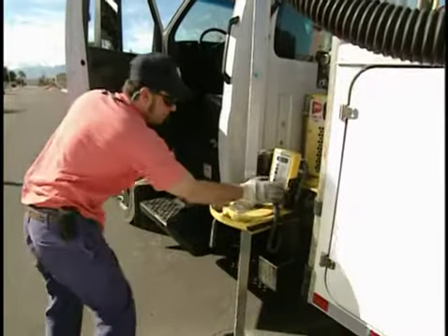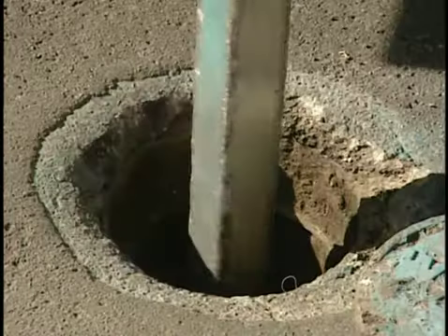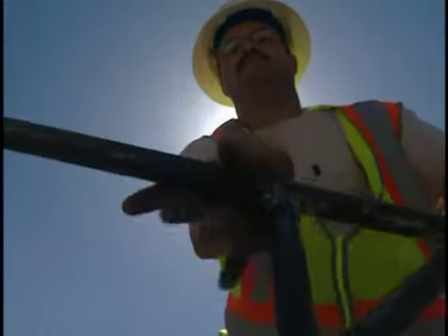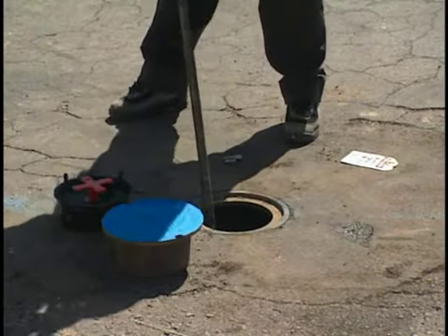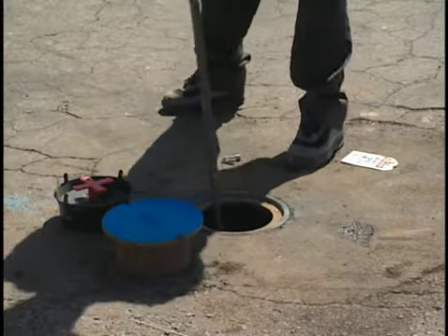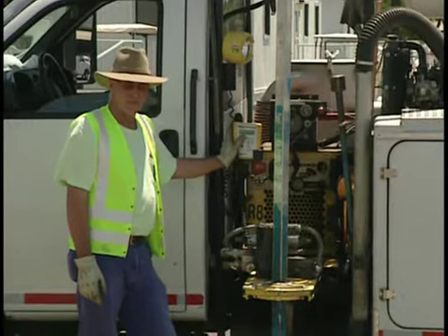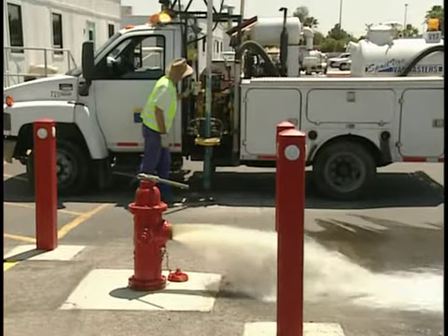When a valve hasn't been operated for a number of years, it may be necessary to use a series of up and down motions to clear the stem threads and accumulation of corrosion on the gates. Close the valve about 5 to 10 turns, then open it 2 or 3 turns, repeating this until the valve is completely closed. If the valve doesn't seat fully on the first try, there may be foreign material accumulated in the depression at the bottom of the valve body. This sediment can be cleared by opening a downstream fire hydrant and then cycling the valve up and down from the closed position so the high-velocity water will scour it away.